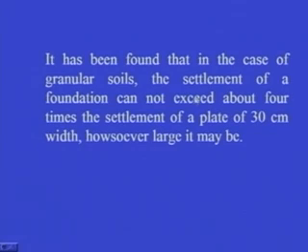It has been found that in the case of granular soils, the settlement of a foundation cannot exceed about 4 times the settlement of a plate of 30 centimeter width, howsoever large it may be.